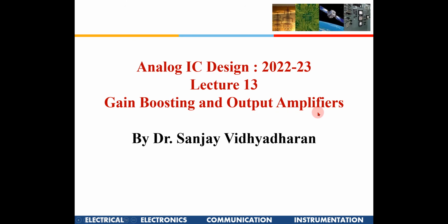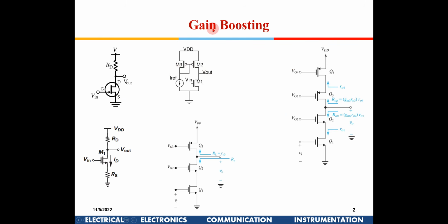In the last few classes we never bothered about making the output resistance close to zero, right? If you don't do that, your final gain will be dependent on the load which we connect, so we don't want that to happen. These are the two issues which we will take up in today's class. So how to boost the gain?